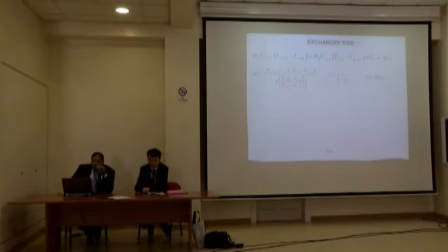And for the first 3 configurations, I repeat, the first 3 configurations correspond to the case where the exhaust gas flows in the inner tube and water in the annulus. And we have varied the outer diameter to have three diameter ratios, outer to inner diameter, of 1.25, 1.5 and 1.75. Here in the two curves we show at the left the variation of the outlet temperature as a function of the water flow rate for the 3 tested configurations, and at the right the variation of the heat rate, or the thermal performance, or the energy rate recovered.